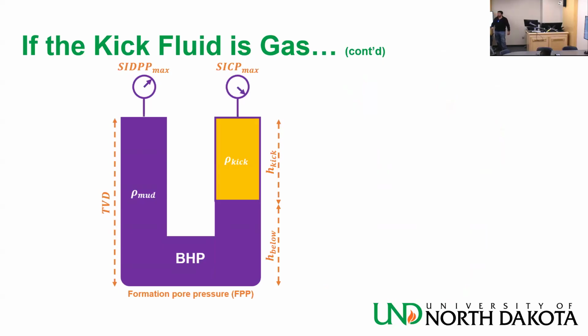And when you have the top of the kick at the surface, basically at the choke, you want to make sure that this is always below MASP. Okay?